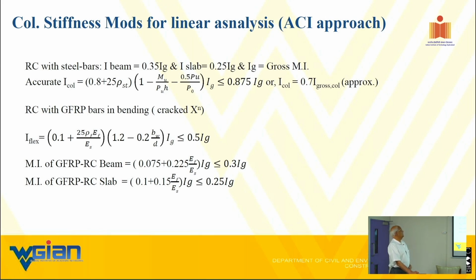Column stiffness modifications for linear analysis. What is that? Okay, what is a linear analysis? What is a non-linear analysis? A linear analysis is that we are not accounting for P delta type effects. If you account for a P delta effect, that becomes a non-linear analysis.